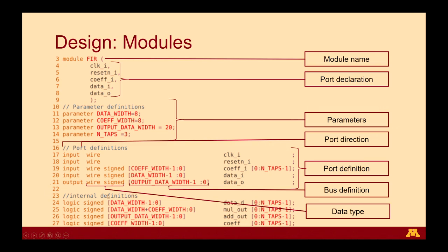This is very similar to your C style of coding, where you define arrays, and even in Verilog, the numbering convention starts from 0. So if you want to define an 8-bit bus, you have to define it as 7 down to 0. How this convention works is, Verilog has two types of arrays, packed arrays and unpacked arrays.